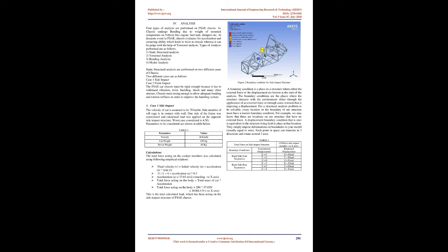For practical reasons, it is recommended that the load on the chassis frame, including its own weight, should be applied at the joints, nodes, of structural members. These point loads were statically equivalent to the actual distributed load carried by the vehicle. The analysis was done in Ansys R17.2. We chose to do 2D shell analysis as it gives appropriate results. Elements selected were 2D quads and 2D tetras. We also inserted dead mass to account for the inertia of the mass of the engine.